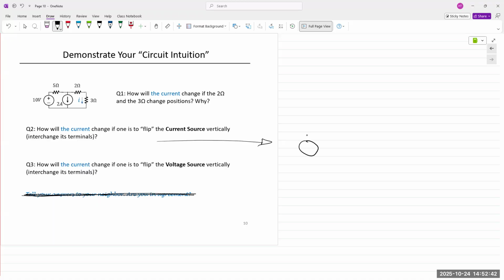If you have a voltage source like this and you flip the current source so that both of them are going up, the voltage source has plus on the top, minus on the bottom, so current goes up. The current source goes up. This bends here, this is coming through here, and if you apply KCL, both of them are coming up, they join up, and so they are summed.